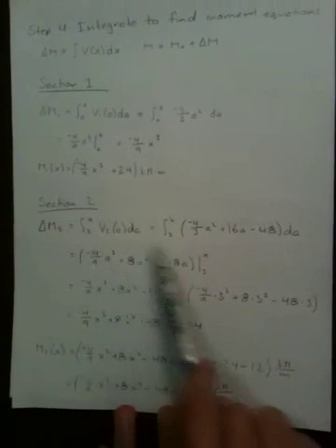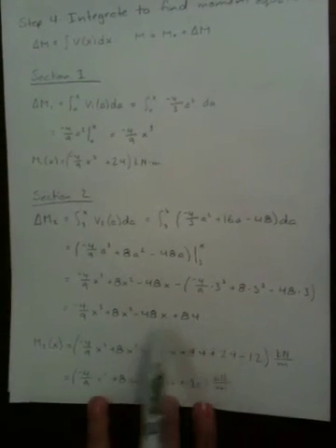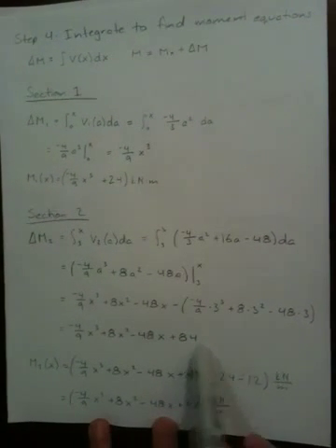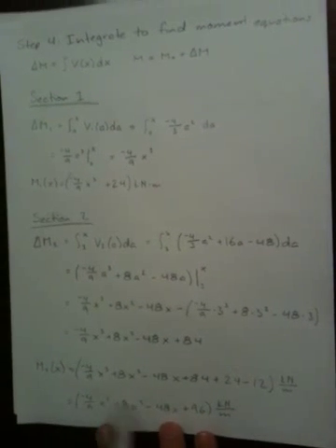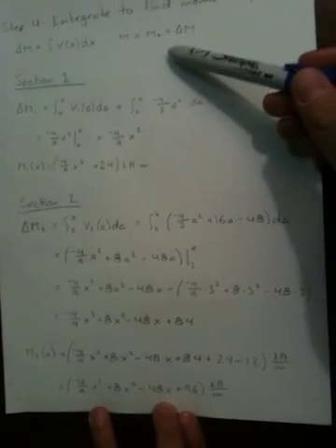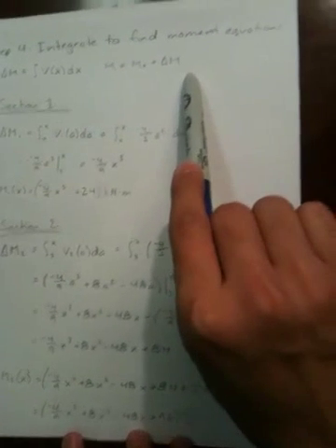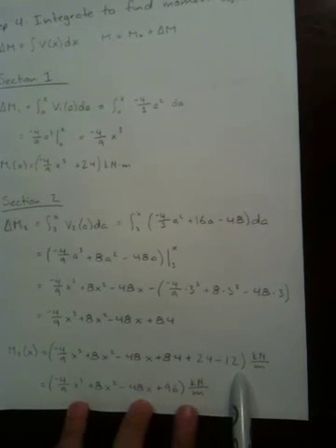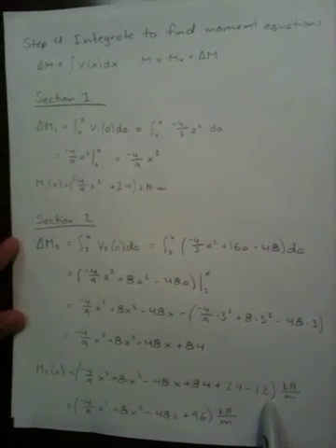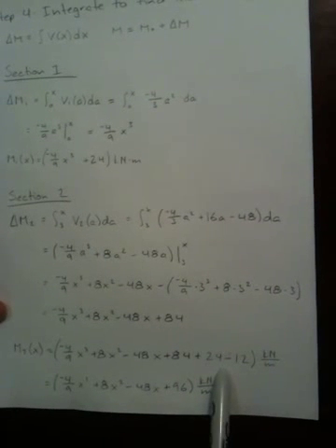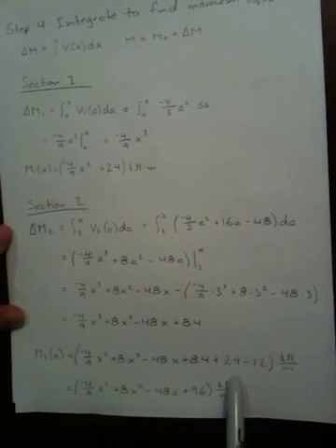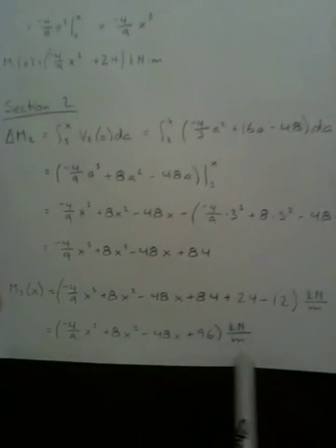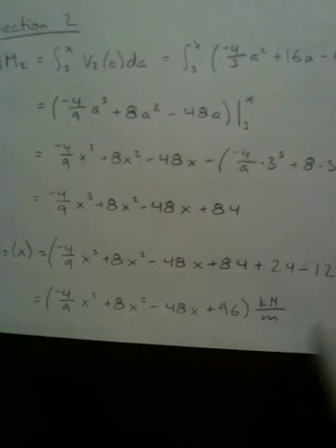Similarly, we work out the math for the load on the right, and this is the expression we get for delta M. Again, we need to account for initial moments according to this expression here, which is the negative 12 from the distributed load on the left and the plus 24 from the couple moment acting at point A. So taking all that into account, we get an internal moment equation which is as such for the distributed load on the right.